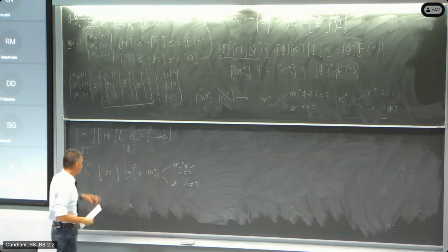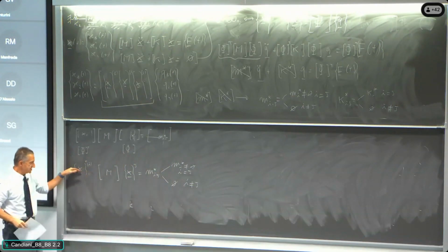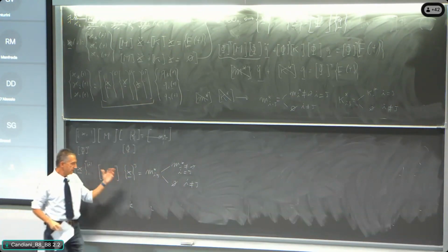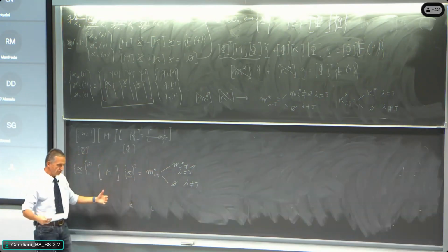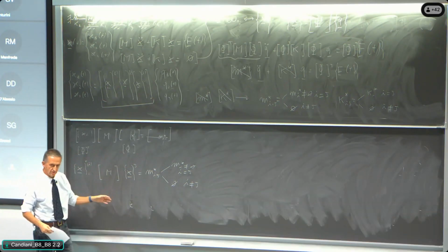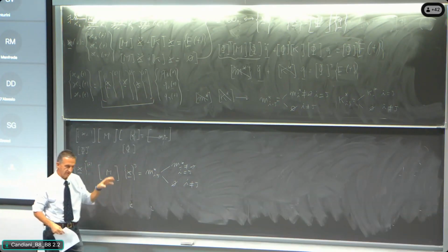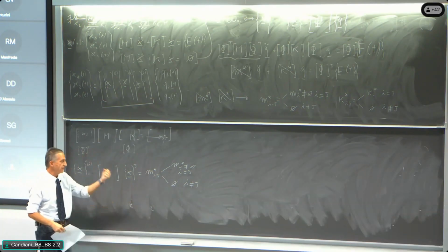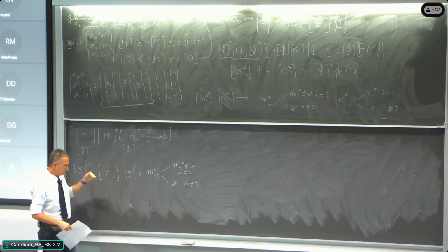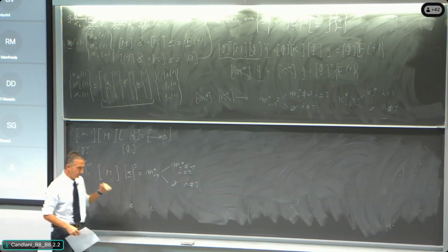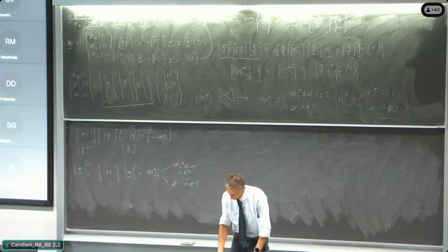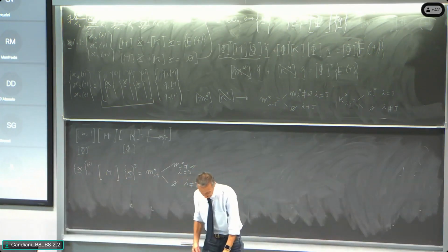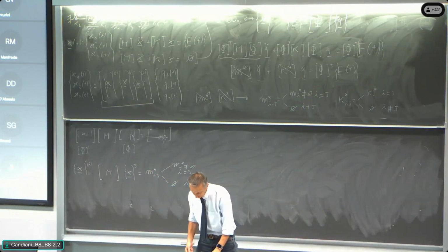Okay? If we are speaking about the same eigenvector, this cross product makes a number that is different than 0. If we're speaking about two different eigenvectors, it is null, because the eigenvectors have the property of being orthogonal through the mass distribution, through the stiffness distribution. So this is the orthogonality property that we studied in the n degree of freedom system.